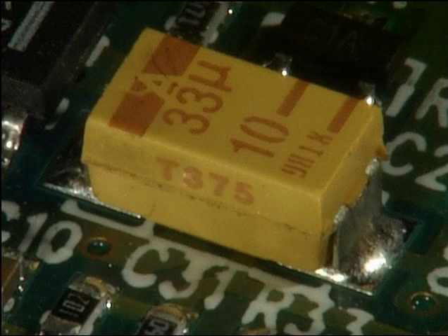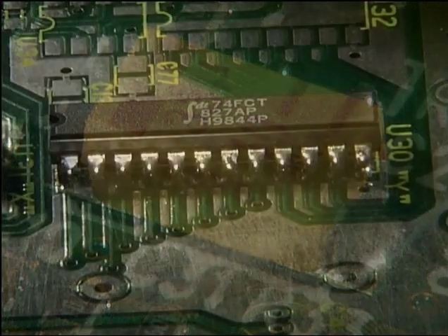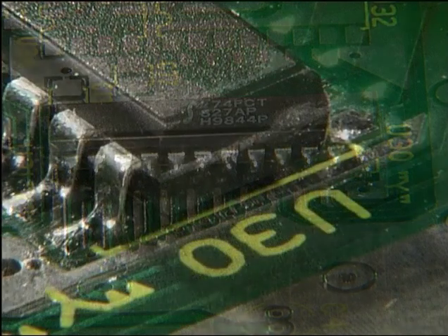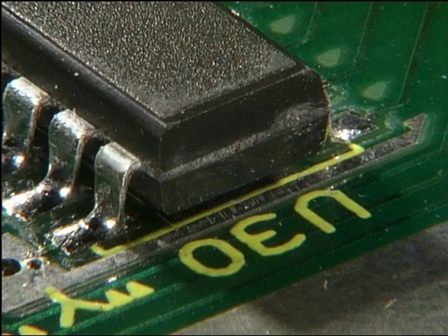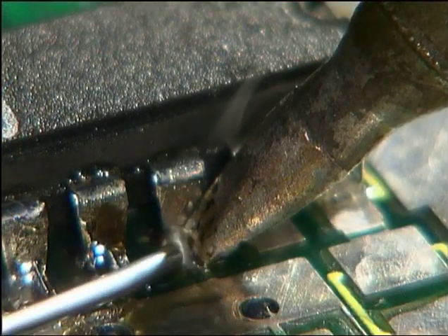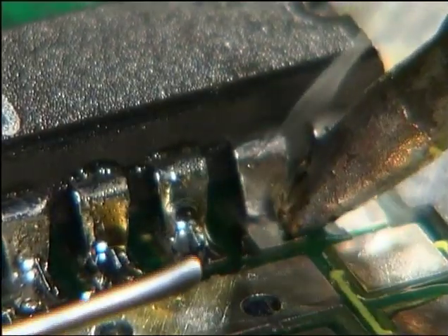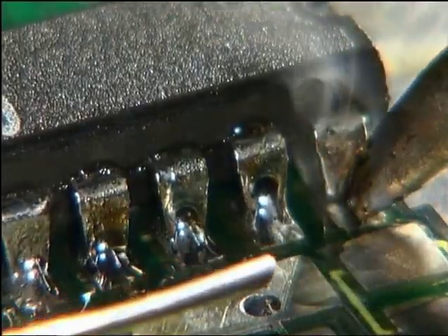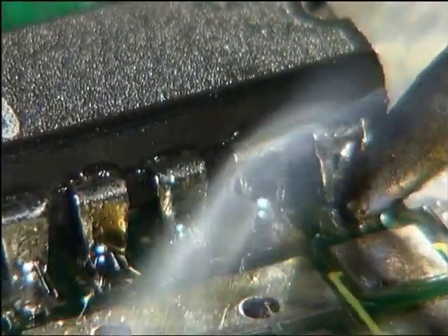L leads are found on molded tantalum capacitors and are formed inward, almost touching the body of the component. I leads are actually through-hole leads that have been cut short for surface mounting. The end of the modified lead is placed directly on the surface land. As you can imagine, this connection won't be as strong or stable as the other types of surface mount leads, and IPC standards do not permit their use on high reliability products.